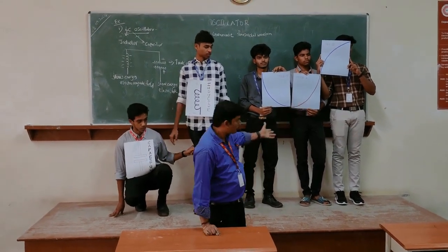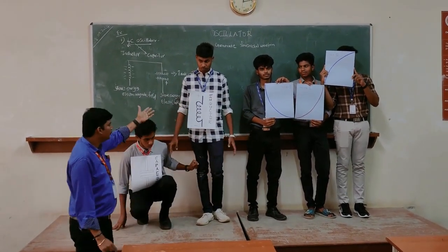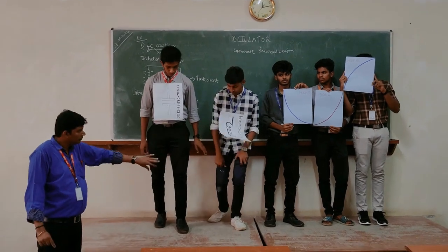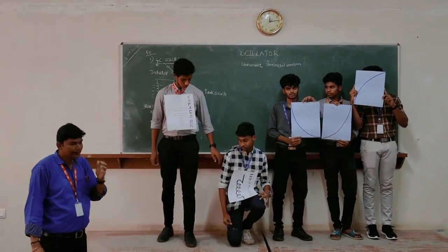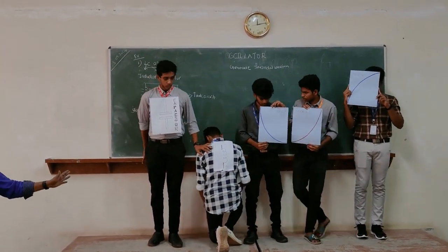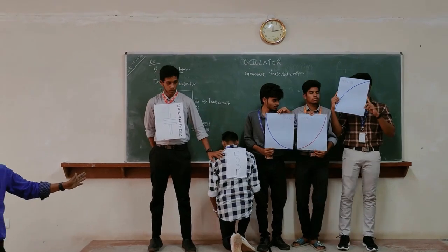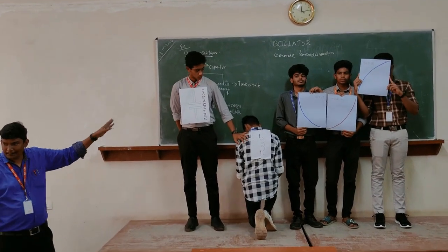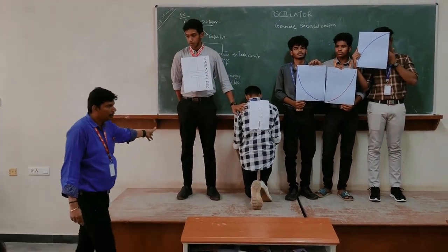Is it right? So now slowly the capacitor is going to charge, because the inductor can change its polarity and it starts growing. Now it loses energy. Now we can understand mode 3 operation. The capacitor is charging in the opposite polarity because of this inductor back EMF.